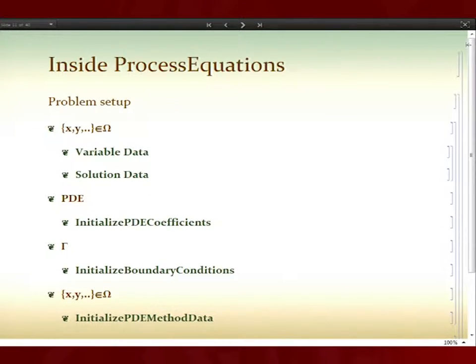Then for the PDE, there is the function called initialize PDE coefficients. For the boundary conditions, we call the function initialize boundary conditions. And then again, for the proper initialization, we call initialize PDE method data. And that will initialize the finite element method. That sounds a bit complicated, and I think I should have an example, right?